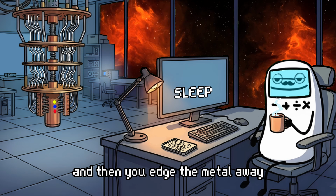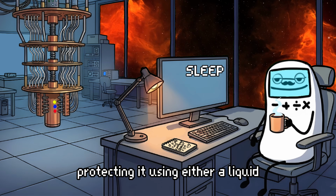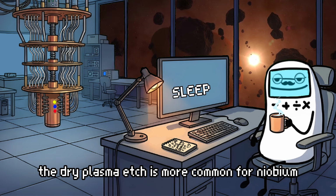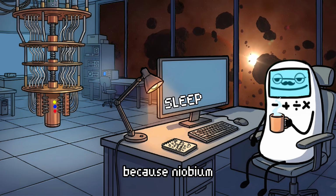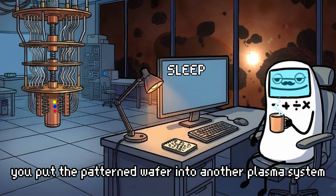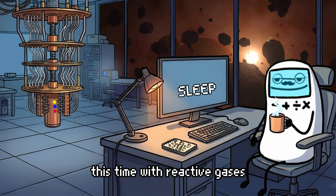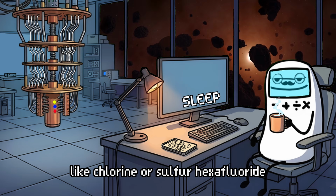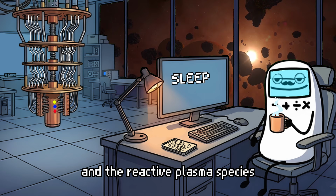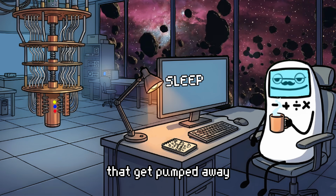And then you etch the metal away everywhere the resist isn't protecting it, using either a liquid chemical etch or a dry plasma etch. The dry plasma etch is more common for niobium because niobium doesn't dissolve well in most wet chemicals. You put the patterned wafer into another plasma system, this time with reactive gases like chlorine or sulfur hexafluoride or a combination of gases, and the reactive plasma species chemically attack the niobium and convert it to volatile compounds that get pumped away.